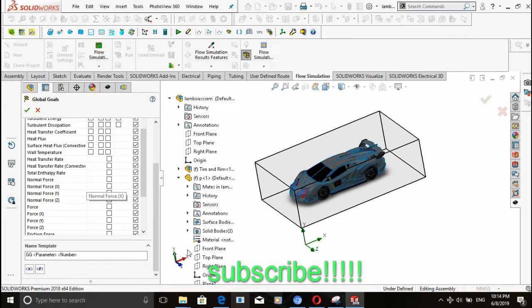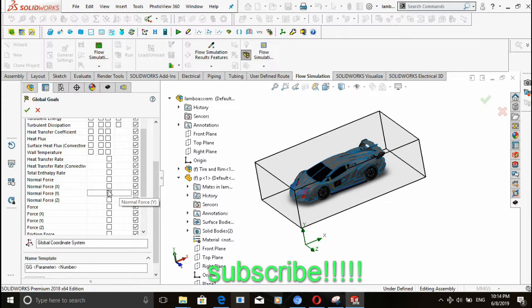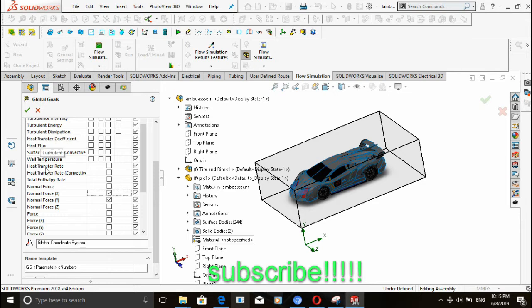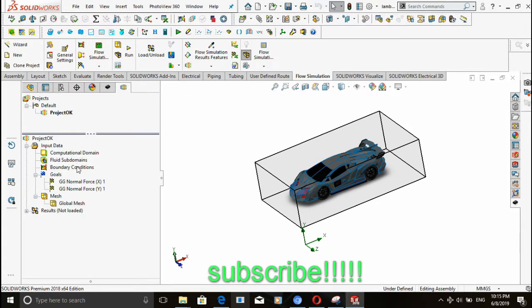If you look at our coordinate system, here we have X and here we have Y. I'm going to choose X and I'm going to choose Y. If you observe it, you're going to discover that X is what I call my drag force, and Y is what I call my lift. So I'm just going to study these two parameters, and I could add other parameters at the level of the result when time comes. When this is done, I'm just going to hit OK.